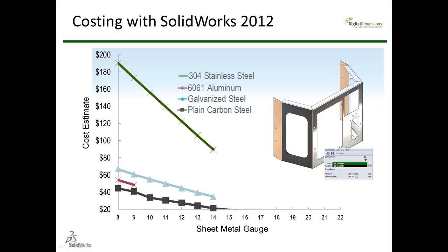On the other hand, if you want to step it up a notch and go with stainless steel, you're going to be paying a premium for the same type of structural results, or same strength results, you'd be getting with plain carbon steel. Now, if you're going to go with aluminum, it's very, very lightweight, hence you have to increase the thickness, and we can use an 8 or 9 gauge aluminum material, which is not so bad if you look at our cost.